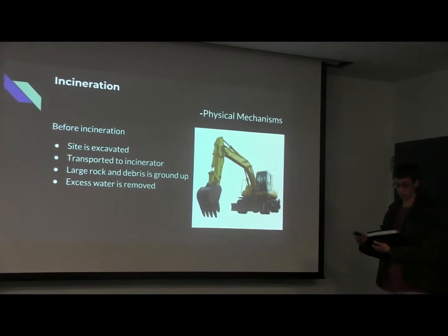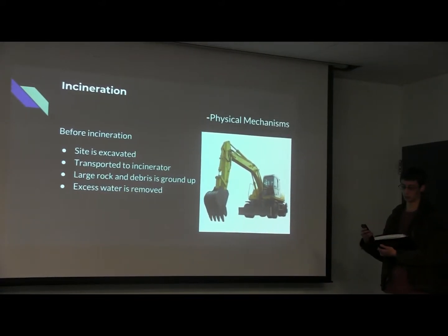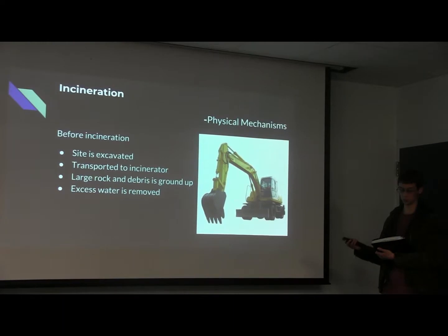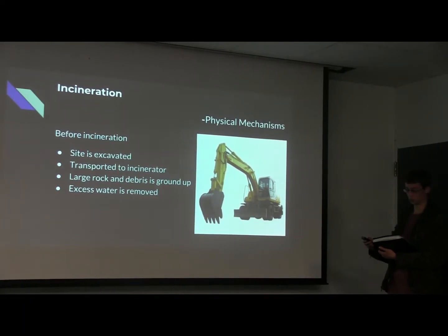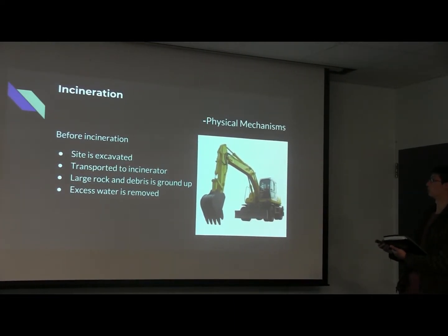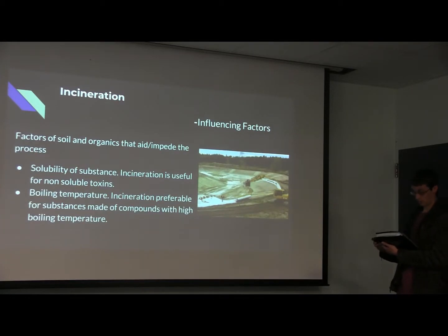Before incineration can take place, the soil must be physically removed and transported to the incinerator. Large rocks and debris must also be ground up and water removed. One strong influencing factor of whether or not incineration is implemented is the solubility of the contaminant itself.